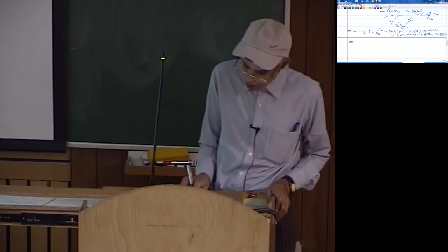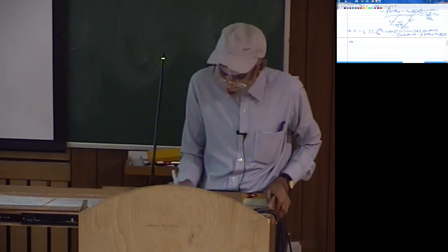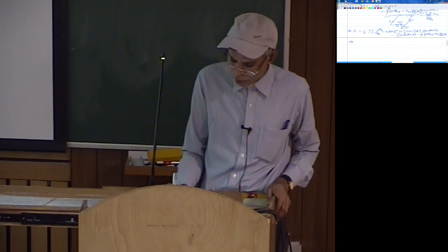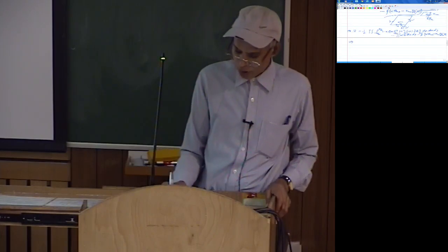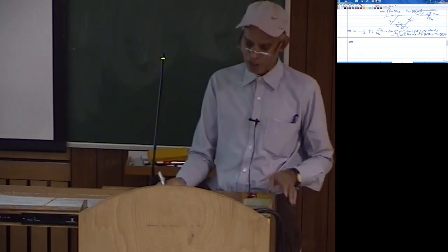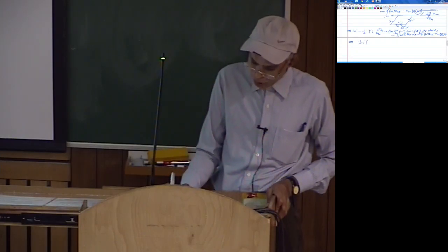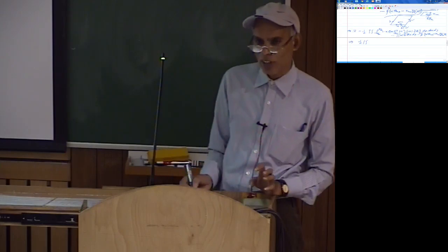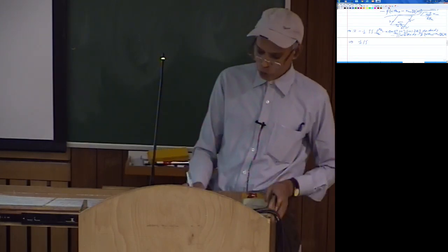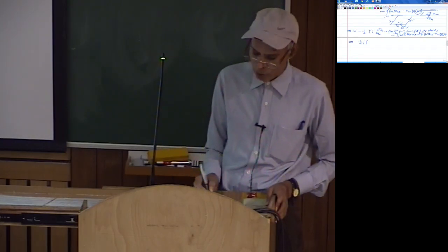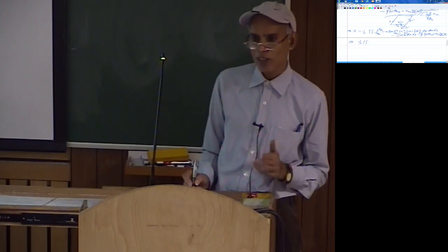And now if you look at it, this z is scalar, so I can take it anywhere. C is a 3 by 3 matrix, this kappa is a 3 by 1 vector, its transpose is going to be 1 by 3, and z is separately a scalar. So you can see that minus z becomes z square, its integration is z cube by 3, and when you put the limits minus h by 2 to plus h by 2, it will work out as h cube by 12.